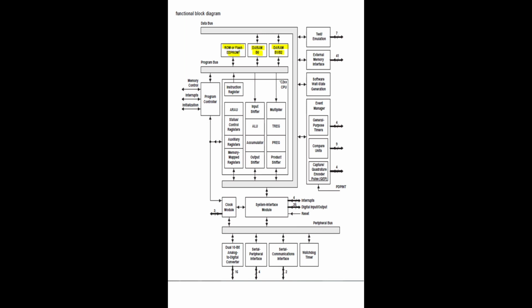B1 and B2 are always only for data memory, but B0 can be configured for data or program. The CNF bit, you will see later: if it is 0, B0 can be used for data memory locations like B1 and B2. CNF is the configure bit; if it is equal to 1, B0 can be